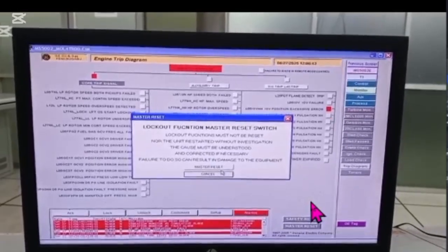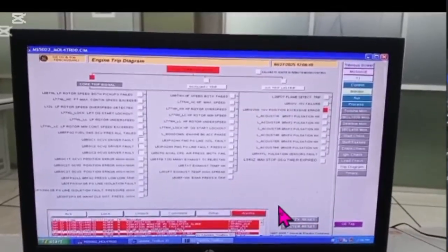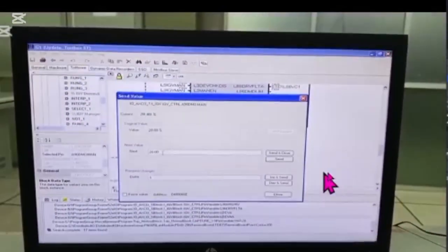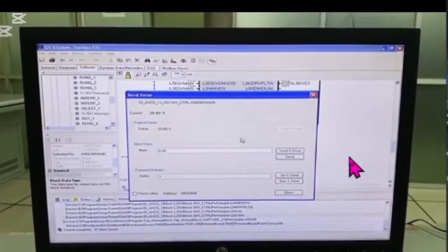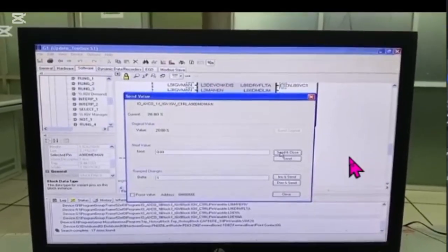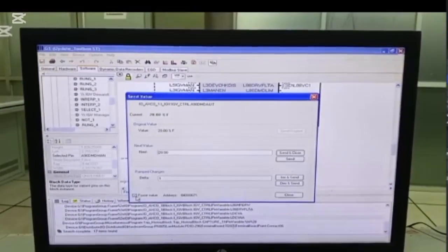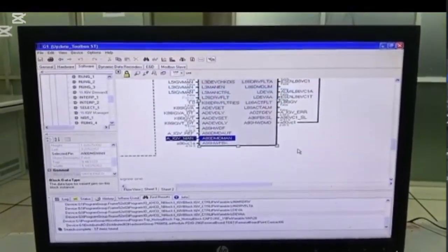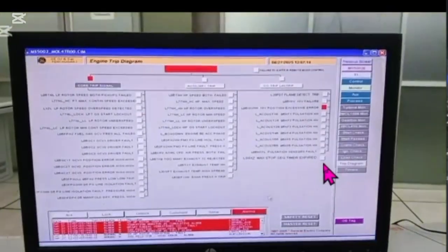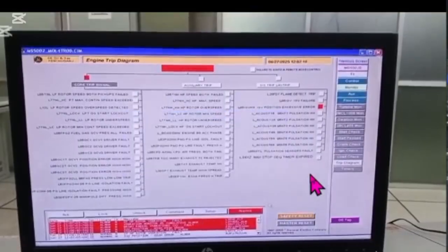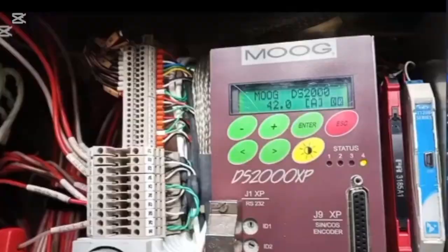You see, when the IGV driven value is greater than 9, then alarm came. Here we applied 20. So we came to a decision that after 9, the demand value shows alarm, and if the IGV opening or set value is lower than 10%, that means 9, it is okay.